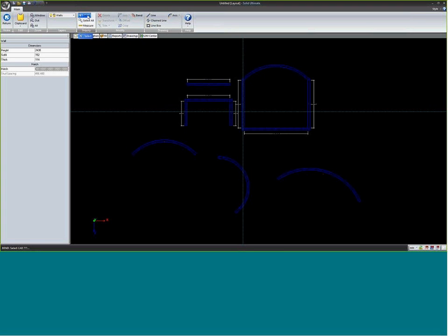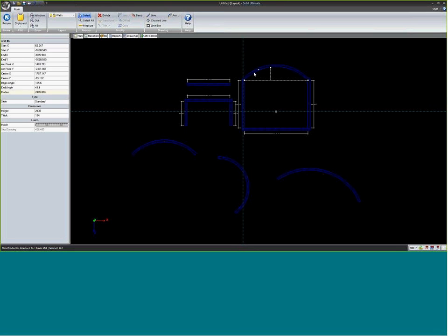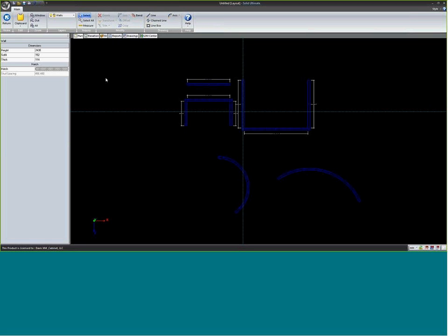If I click on my select tool, pick an individual wall, and now I can get access to the delete option, so I can delete a radius wall. If I click on a wall and hit delete, it will click out. I can also select a wall and hit the delete key on my keyboard, and it will delete the wall. Another way of getting rid of walls, if I'm in the wall mode, I'm still in the wall mode with these wall tools, I can draw a box around multiple walls and hit my delete key or hit the delete button on the ribbon bar.